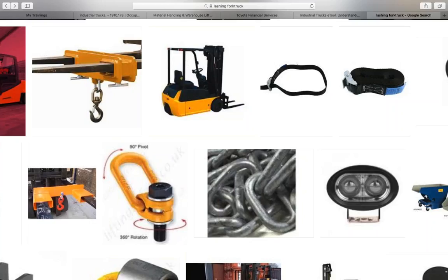The three greatest hazards with chains are most often what? First of all, the weight. It becomes an ergonomic issue, an ergonomic nightmare, right, with the weight. Second, pre-inspection on a chain has to be done link by link.